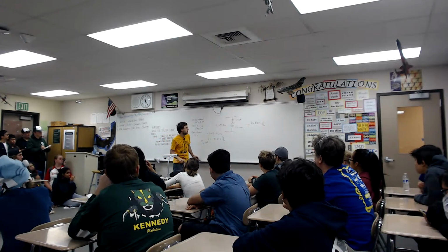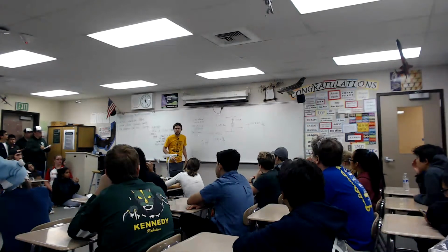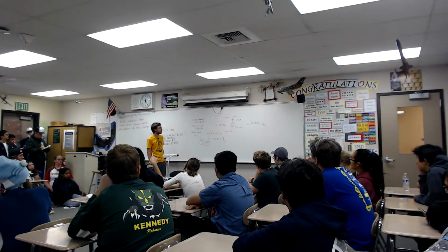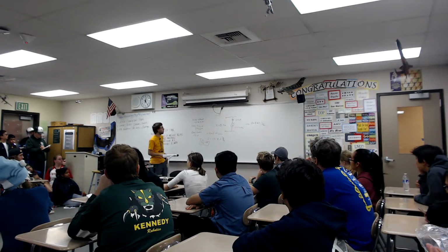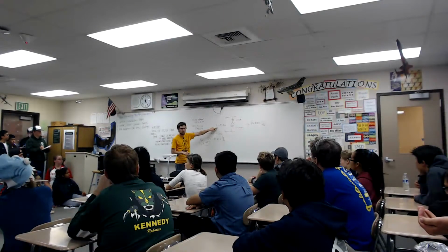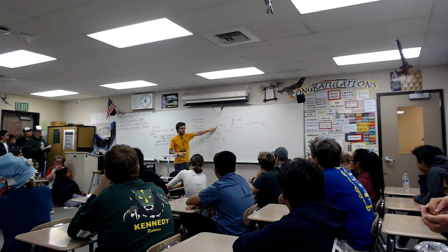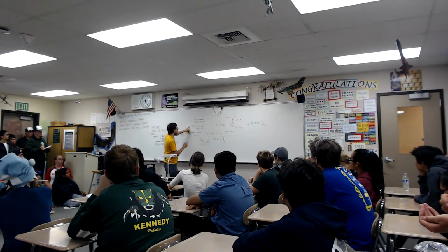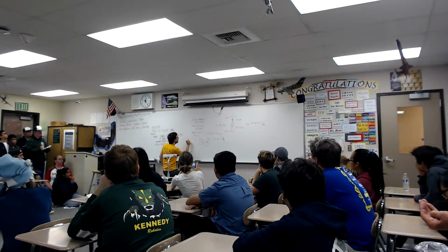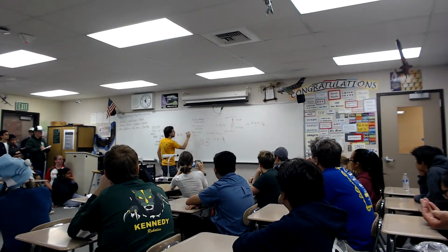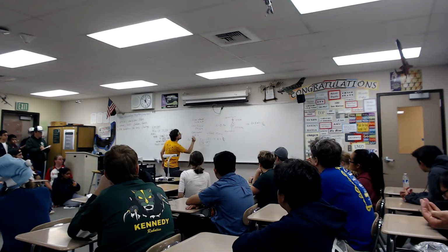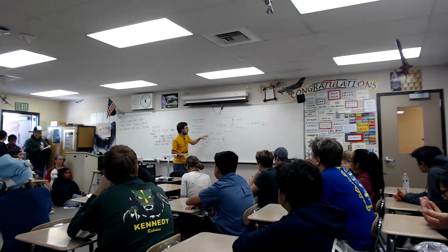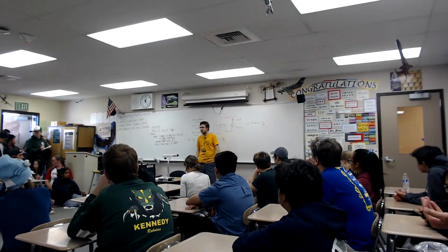So now let's pick another one. Yep, perfect. We're going to pick another known operating point. This is stall, so we'll have our stall torque, and we know our stall current, and so we can compute KT. That one's pretty straightforward. So KT would be stall torque over stall current. Okay, and then it looks like we need KV next.